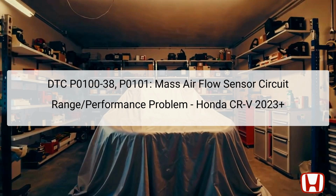The MAF sensor plays a crucial role in determining the amount of air entering the engine, which is vital for efficient combustion. By measuring airflow, it provides the PCM with real-time data, allowing it to adjust fuel injection and optimize performance. If these parameters are not met, it can lead to poor engine performance, increased emissions, and potentially engine damage. Understanding this diagnostic code is critical for proper vehicle maintenance and repair.